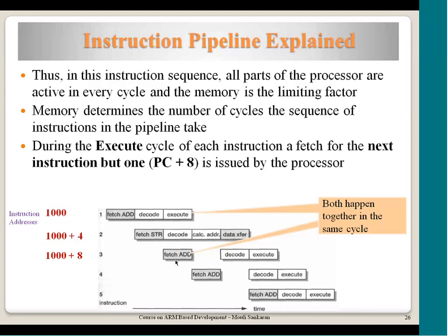When we talk about some instructions and their impact, we will be touching upon this. So please remember this particular case: for the instruction at 1000, R15 is pointing at 1000 plus 8 to fetch the instruction from the memory. This is the anomaly that we should be aware of as an assembly programmer.